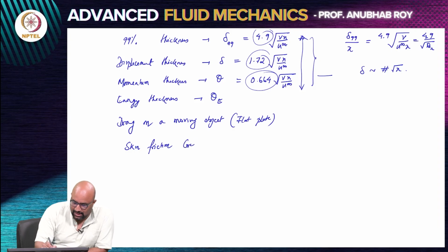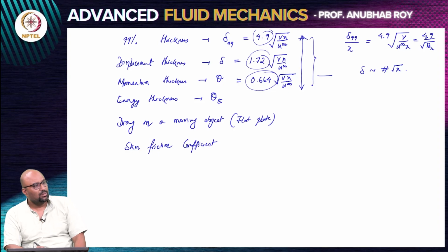These are crucial in order to see the effect of boundary layer, because the starting point of boundary layer analysis is that there is a thin layer of fluid sticking to the surface where viscous effects are important and dominant. So, this entire exercise is targeted now to give us a measure or a value for what is the resistance that the surface offers to the fluid by making it adhere to it.